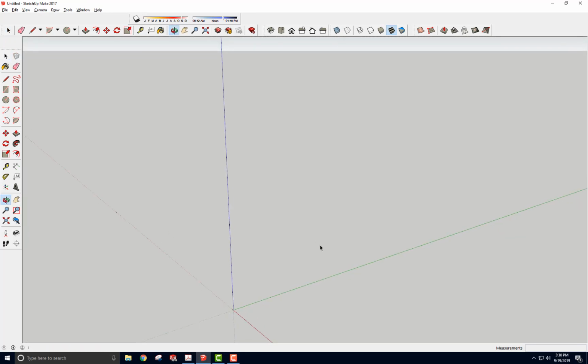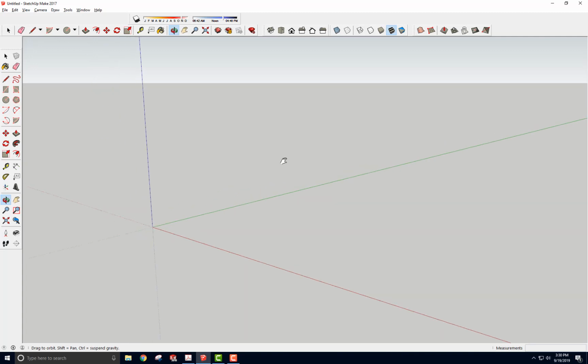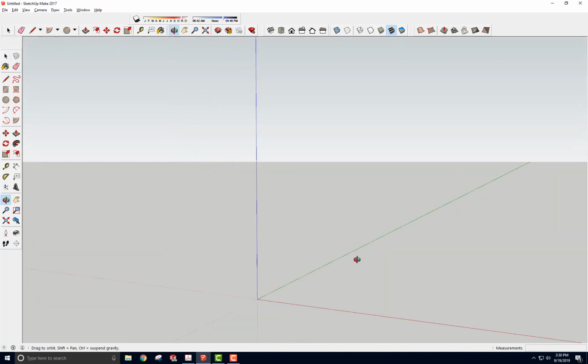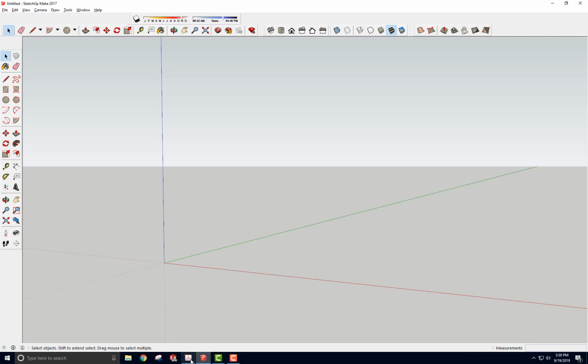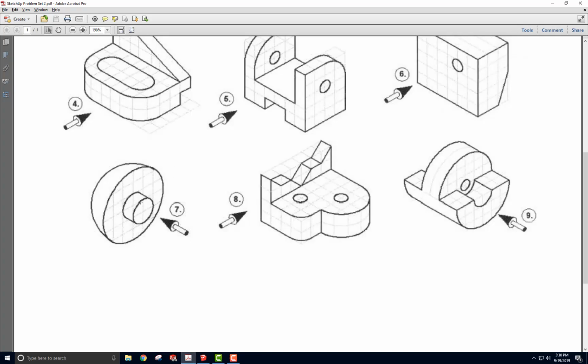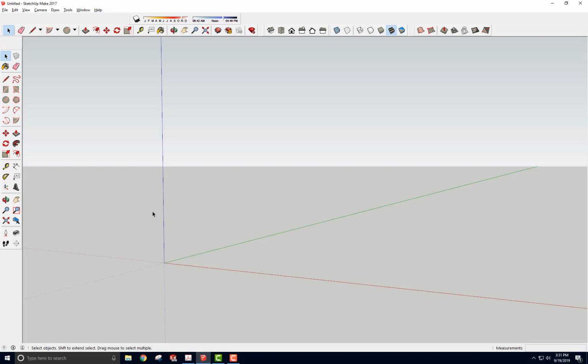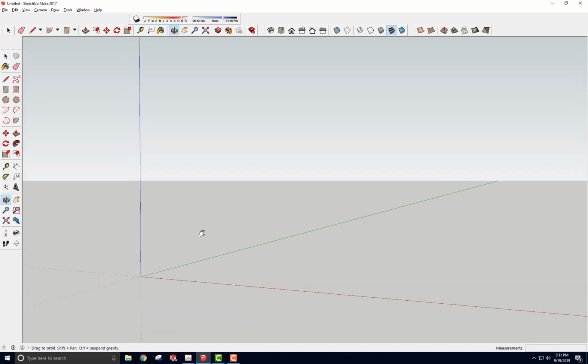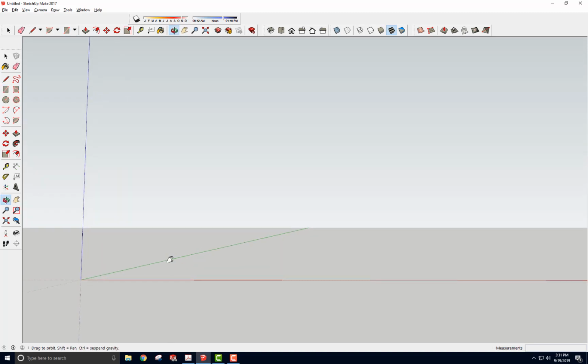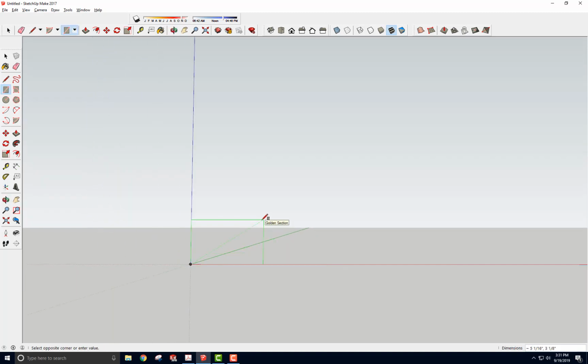What I'm going to do is create a surface to draw on for this one, because this is specific. I need to create a picture of a quarter of this as just a thin paper sketch, and then I'm going to revolve it around 360. That's the plan. I'm going to start with a surface to draw on. So I'm going to start here and bring up my surface so that it's 3 high and 4 deep. I'll say this is going to be 4, 3. There it is.